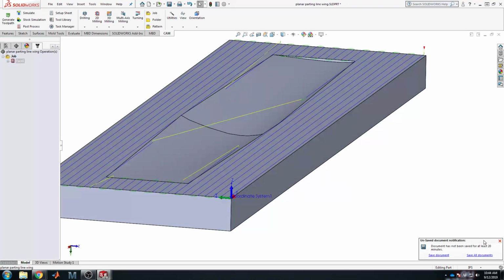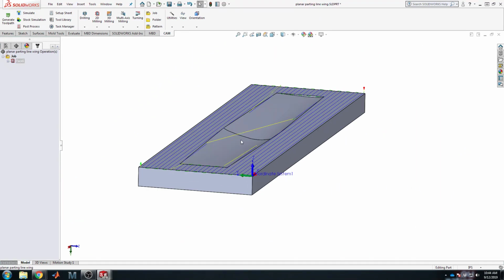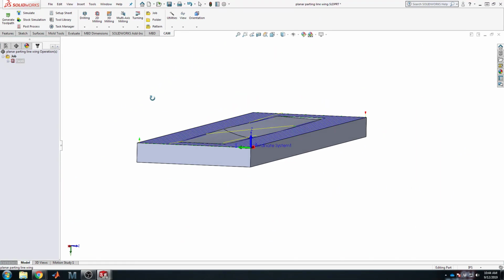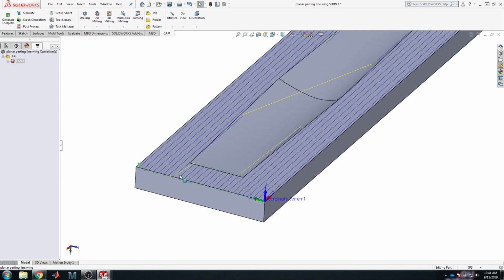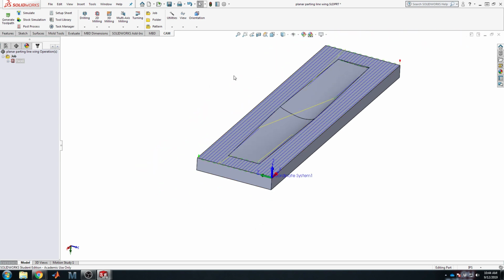Now this again comes down to the fact that we have a flat planar parting line. This is why it's such a big deal for machining. It's very, very simple. It's very fast. We're using a flat tool to make a flat surface, so the offset can be huge. And yeah, we're good. But certainly this will not alone make the part we want. Everything on the inside here is untouched.